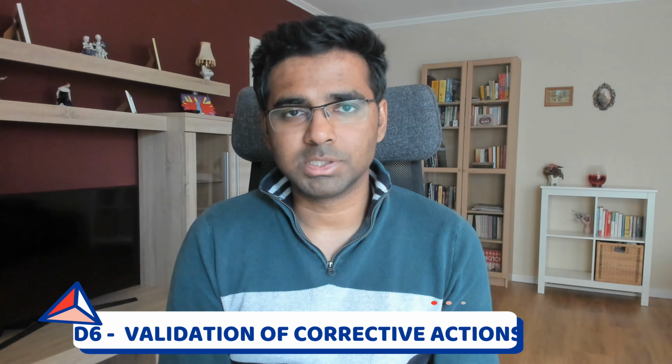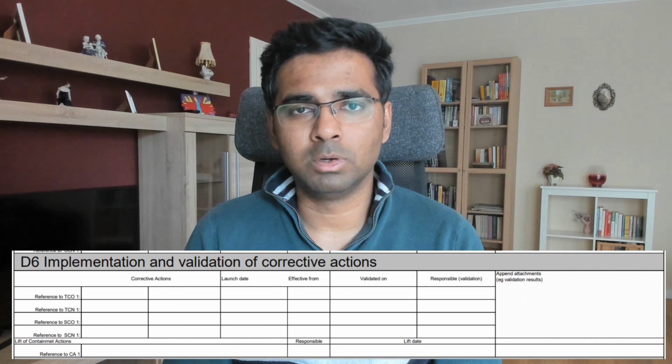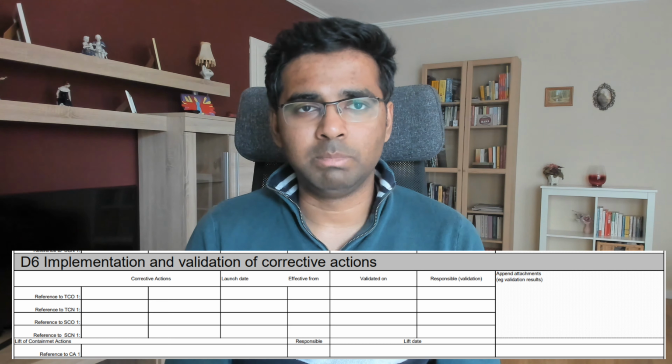After the corrective action is implemented, it should be verified for a certain time period if the corrective action is effective or not. You can decide based upon the issue how long you have to do this verification. It can be verified for a certain time period or batch or quantity of the parts produced.